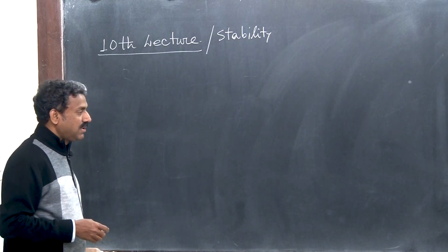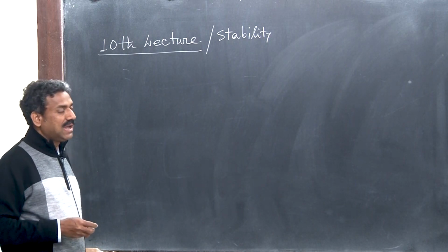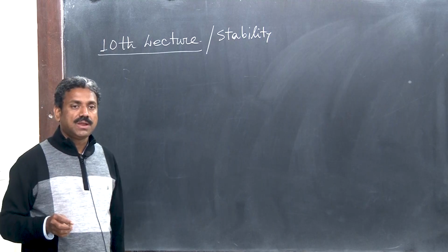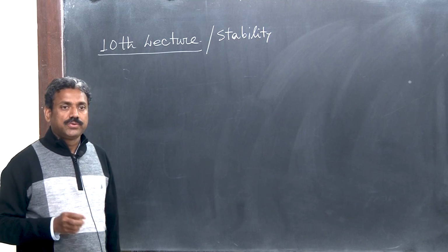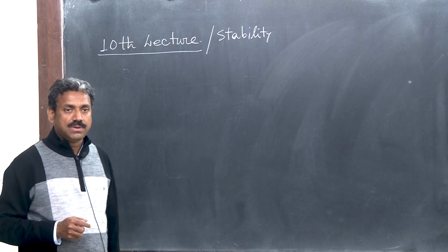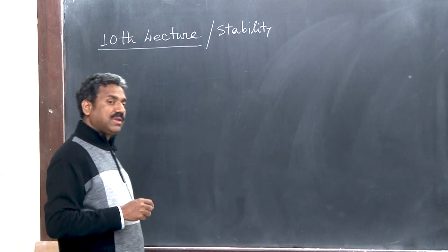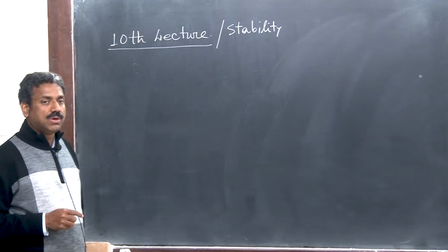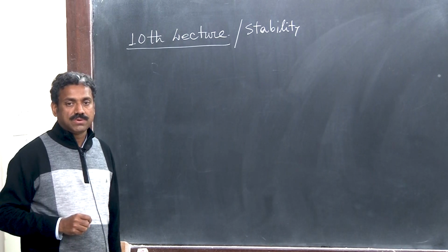And then the next step, since we are following the energy approach, we have to derive the potential energy function. The strain energy component we have already derived. I will write down the expression shortly. Then we are working with the expression for the work done.